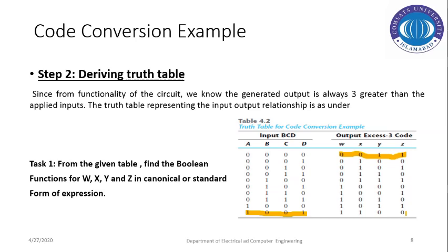Now the important thing is that since the input is a 4-bit combination, we've got a maximum of 16 combinations. What happens to the rest of the combinations that are greater than 9? Are they valid BCD numbers or not, which we have already discussed while adding the BCD numbers in our previous sessions. If those cases are applied at the input, what would be the status of the output then? Since they are not valid BCD numbers, the output should be undefined in all those possible combinations.